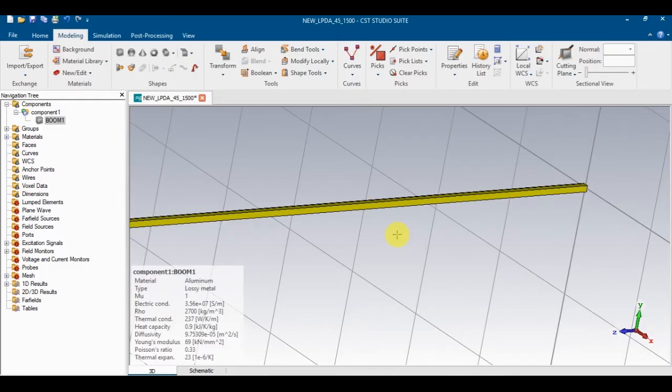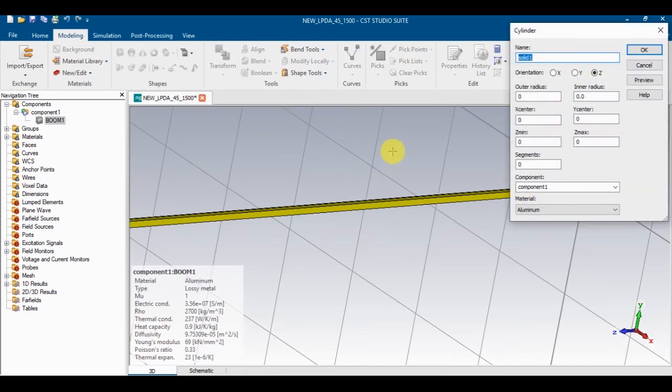Further, the number of elements is 13 and the length of the first element is, we will enter, but as all these elements are cylindrical in shape, let's pick cylinder and press escape. Okay, so we will give the name as element ELE1, as orientation will be at x and -x.